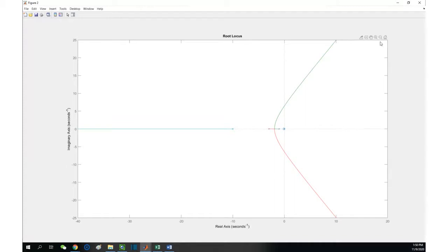What we do is, once again, locate a point. Locate the new closed loop pole point. This time is not by locating the gain, because the gain is the one we are looking for, right? What we know this time is not the gain anymore. This time we know the zeta, 0.503, right? So we are trying to move along the root locus to find that particular zeta value, right? Let's go. Okay, let's go. Where is it? What's the zeta now? Anyone can read?